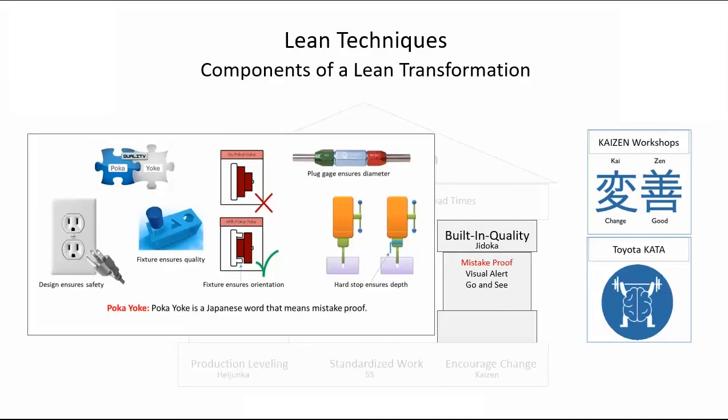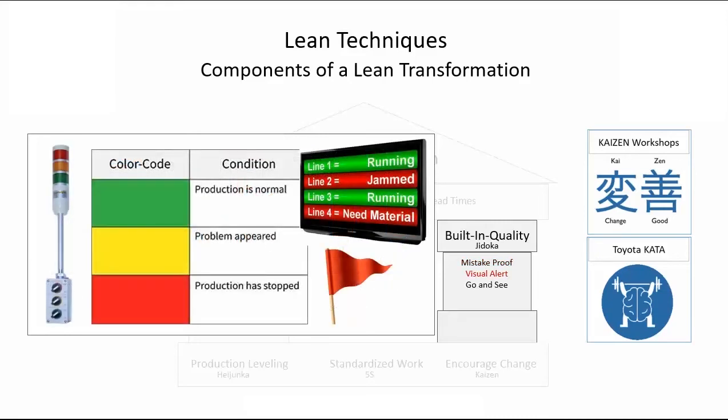These are some examples of mistake-proofing. When a quality defect is observed and understood, we want to go back and attempt to find mistake-proofing ways to prevent the defect from reoccurring. Poka-yoke is a Japanese term that means mistake-proof. When the potential for a failure cannot be totally eliminated, we want to at least detect and communicate the problem before it reaches downstream processes or external customers.